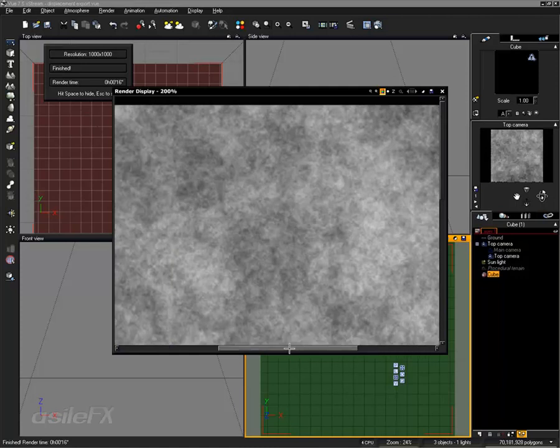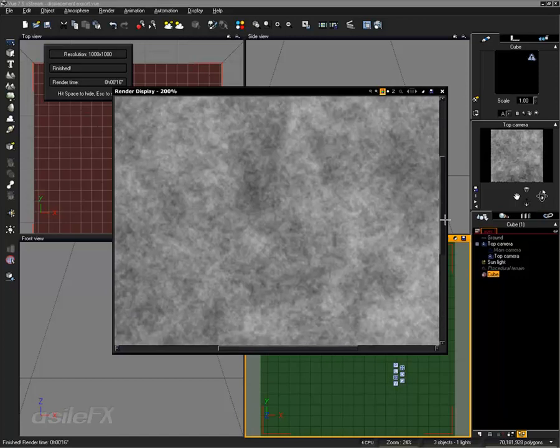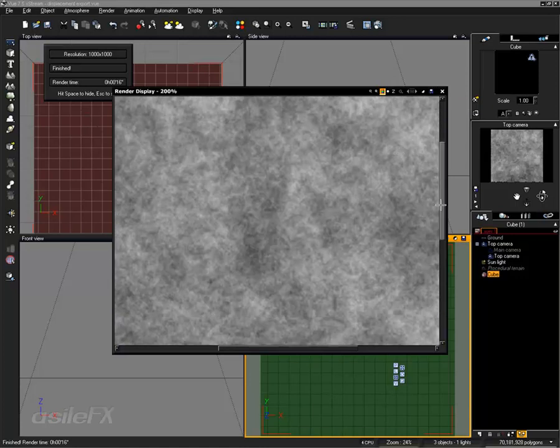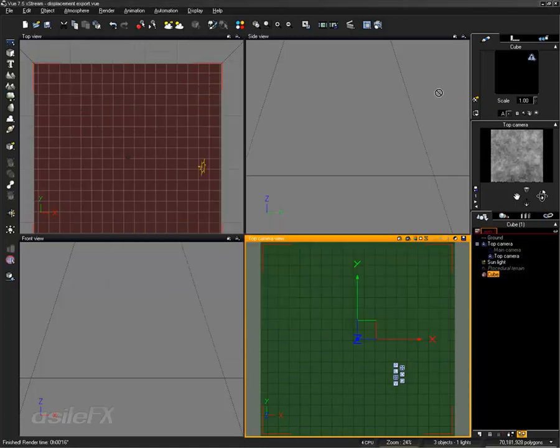Another solution is to render larger than you need to and scale down the image. Since these do render very quickly and are network render compatible and multi-core, so it's not connected to those export functions which only render on one core, it's definitely a possibility to use a different resampling and render sometimes even twice as large, and then reducing the scale.